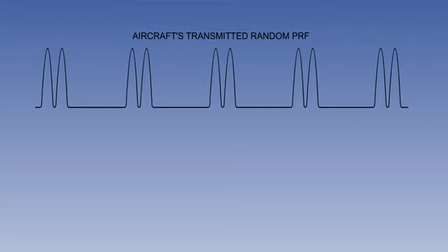This differentiates its pulses from those of other aircraft. The use of twin pulses ensures that the receivers never accept matching randomized single pulses which could possibly emanate from other radars, ignition systems, or lighting.